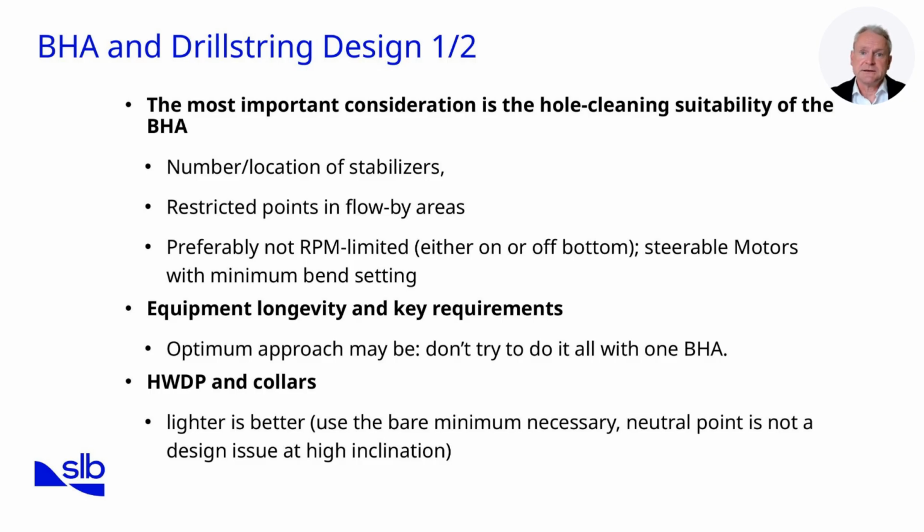Ideally, the BHA should operate effectively both on and off bottom, with steerable motors set at minimum bend to balance steerability and efficiency. Equipment longevity is another key issue. Long runs in ERD wells require durable components, an approach that may necessitate multiple specialized bottom hole assemblies rather than attempting to achieve all objectives with a single assembly. Regarding drill collars and heavyweight drill pipe, lighter designs are generally better. The neutral point is less of a concern at high inclination, so reducing weight helps lower drag. Altogether, the BHA should be tailored for long intervals, cuttings transport, and tool endurance.